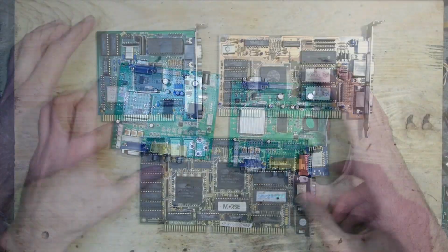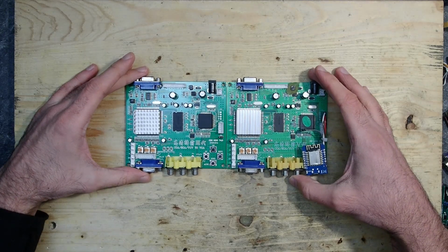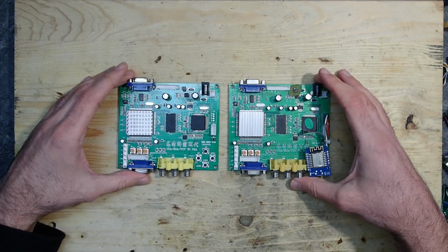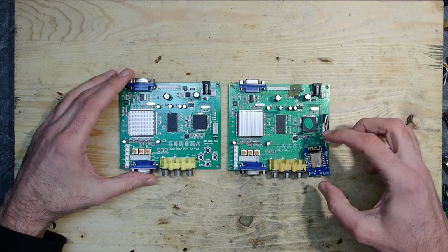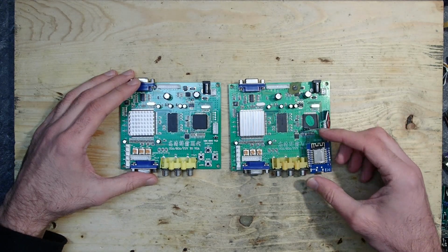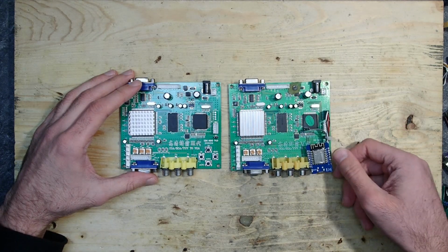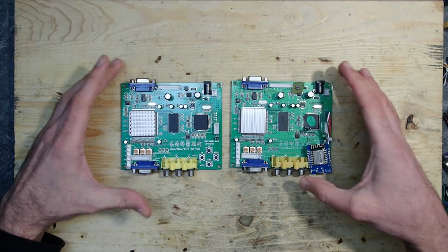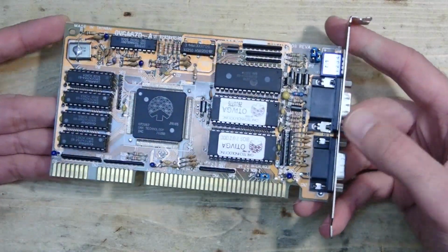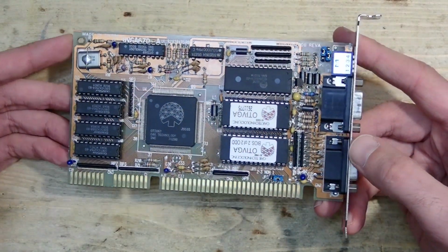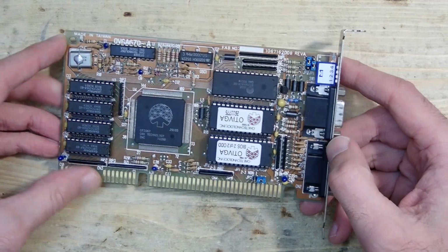However, the GBS-8200 supports in the unmodified state only 15 kHz, and using GBS-Control, 21 kHz seems to be an absolute maximum. 24 kHz is way out of this limit. That's why I couldn't get any image using it. The question is, why does this card deliver such high frequencies? This remains an open question.